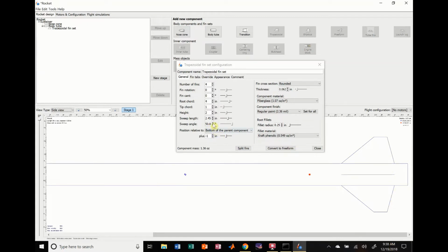And if you keep your fins like, say, like this, it's going to hit fin first, which is usually pretty weak. So it might actually snap off one of your fins. So what we typically do is we try to shift the fins up on the body up to 1 inch, but usually for smaller rockets we choose about 1/2 an inch. That's pretty typical.